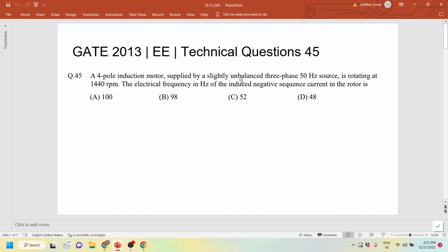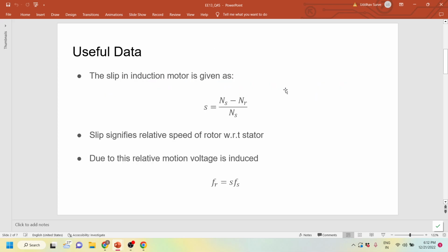So when there is an unbalanced 3-phase system, there are positive, negative and zero sequence currents. The characteristic of the negative sequence is that it is in 3-phase only, which maintains the 120 degree phase shift between the individual 3 phases A, B, C, which are phase shifted from each other by 120 degrees. So let us take the example given in the question, where an induction motor is fed by a 3-phase voltage source.